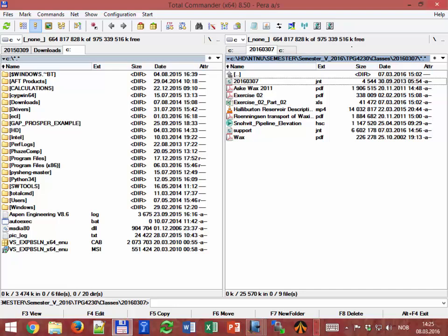Okay, we had the standard flow rate of oil and the standard flow rate of condensate, and then we said we had also the density at standard conditions. From there we can get the total mass flow rate, and then with the composition we can get the molecular weight of the mixture. Okay, and with the molecular weight and the total mass flow we could get from there the molar rate.